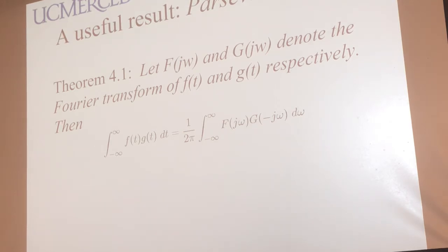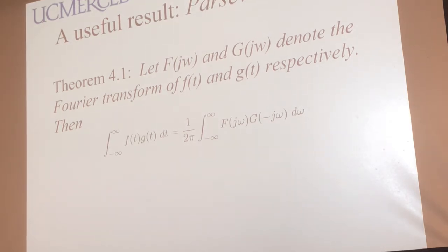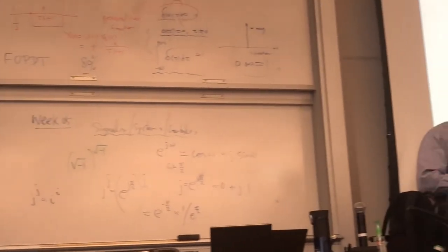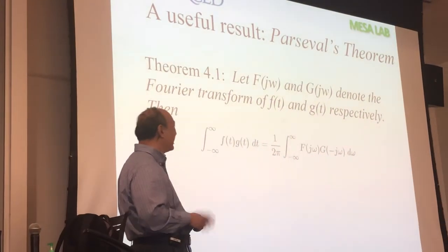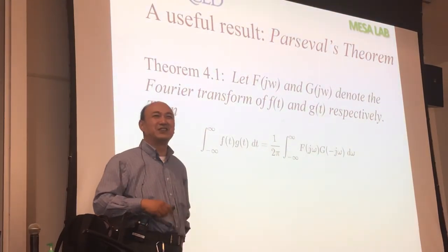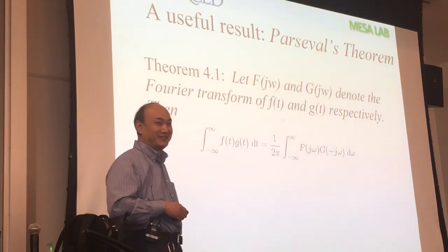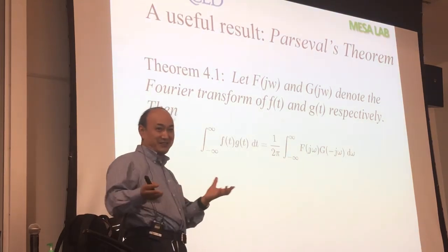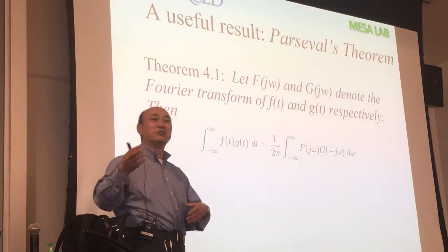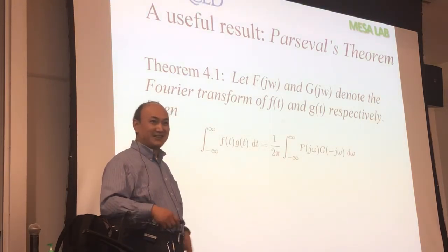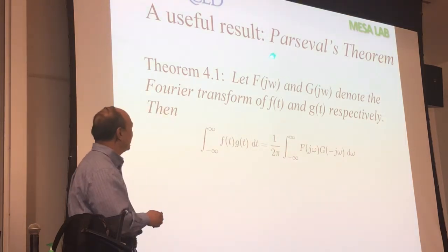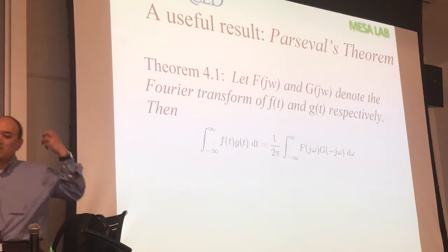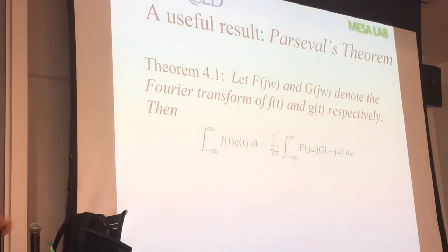So in the time domain, the total of the squared signal added together is the energy of the signal f of t. It's the same as what you see in the frequency domain. The energy didn't change, it's just that you see it in a different domain. Do you get it? So this Parseval theorem is beautiful, right? It connects your frequency domain and time domain in such a nice way.